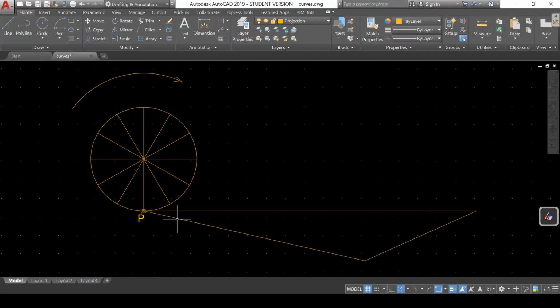And now we will divide this. This is a standard length line, 120 mm we have chosen, and each division will be of 10 mm. So let us divide this line into 12 equal parts and then join the lines parallel to this from those points. So like this, 10 mm each. So we will divide this like this into 12 parts and draw lines parallel to this from these points, so that we will get the equal divisions on this line which is not of standard length.